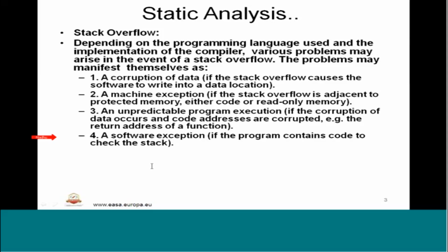This can be done with the help of review of the source code and the map file, and overflows should be addressed by requirement based testing as well as integration testing. Basically, it is done during the integration testing. It could be software integration on the actual target. That stack analysis and stack overflow check will be performed on the actual target.